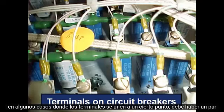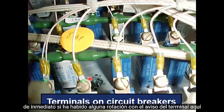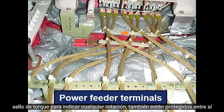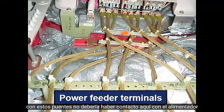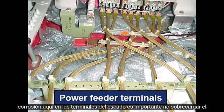In some cases, where terminals attach to a certain point, there needs to be a torque. So in this case, you'll notice that there's torque seal to show the mechanic right away if there has been any rotation with the terminal. Notice here, these power feeder terminals also are guarded against rotation and use the torque seal to indicate any rotation. They're also protected from each other with these bridges. There shouldn't be any contact here with the power feeder terminals. And notice they also are shielded, so there shouldn't be any corrosion here on the shield.